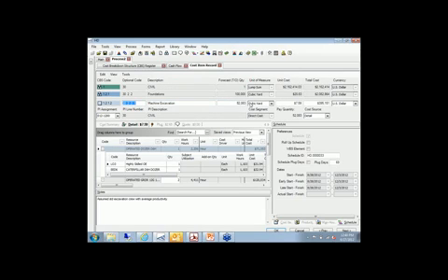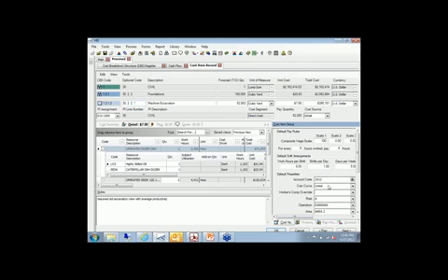Well, how does hard dollar know how that's going to flow? If Primavera gives us the start and finish date, you can see it there, August 28th to December 3rd. Well, is that going to happen a little bit every day? Is it going to happen, we're going to kind of ramp up and ramp down? So we can use the cost curves you're familiar with in Primavera, or you can create your own cost curves on the hard dollar side. Okay, so you can use our predefined curves, or you can create your own custom curve and define how that spread is going to happen.